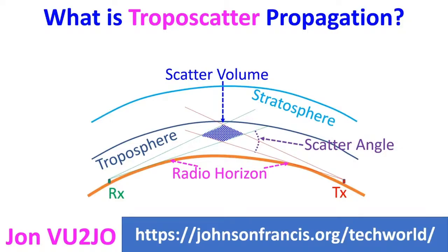Troposphere can refract higher end of the radio spectrum. HF is reflected typically by the ionosphere, much above the troposphere. Tropospheric scatter was used mainly by the military prior to the era of satellites. When the transmitting and receiving stations point their antennas to a common scatter volume in the troposphere, as shown in the illustration, troposphere refracts the signal towards the receiving station.